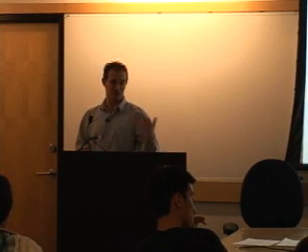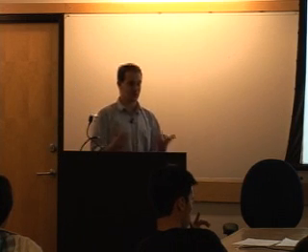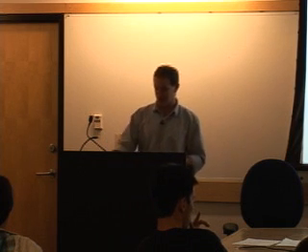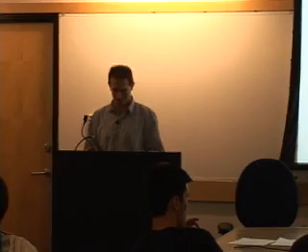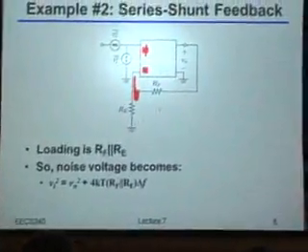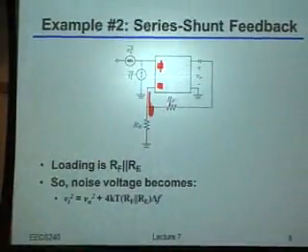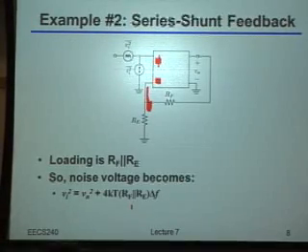Okay, so as I was starting to say, we've added all this resistive feedback in, and although it's certainly playing an important role, which is doing the feedback, of course, those resistors are adding noise, and in fact, you could even argue are adding power into our circuit. And that's kind of bad, right? In particular, let's say I wanted to minimize the voltage noise due to these resistors, right? That would basically mean that I have to use very small feedback resistors.